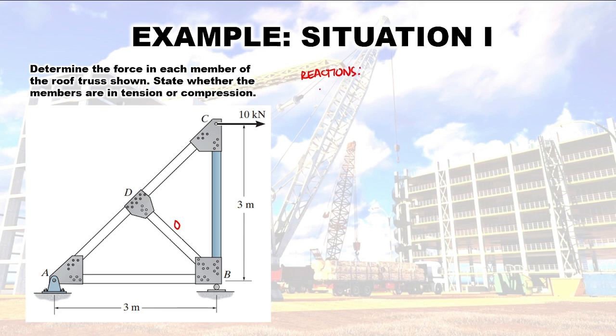Okay. So our reactions, we have your hinge here. It is going upwards, AV, then you have AH, then you have here BV. You can already do summation forces horizontal equals 0, right positive. AH, this one is going to the right, so positive. Then we have 10 here, which is also going to the right, so positive. This one is equal to 0.